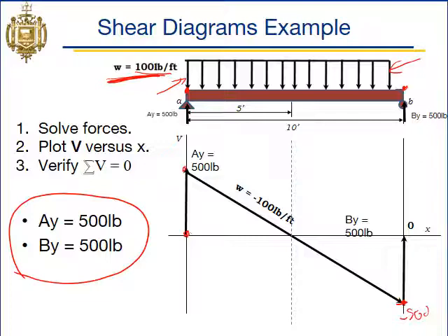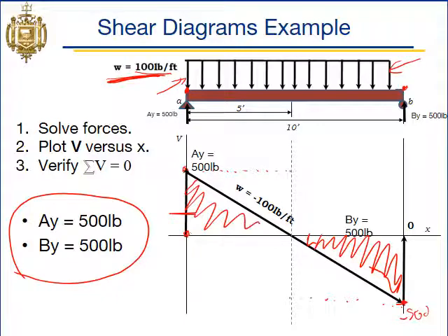One thing to look at here versus just having that single point load is that the point load had rectangular blocks for area under the curve of the shear diagram. Remember, area under the curve of the shear diagram is negative between the 0 line and the shear line when below, and positive when above.